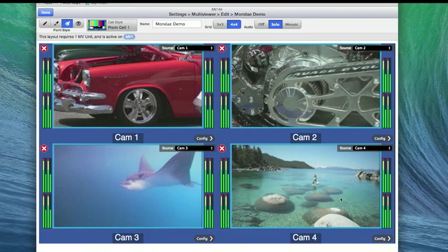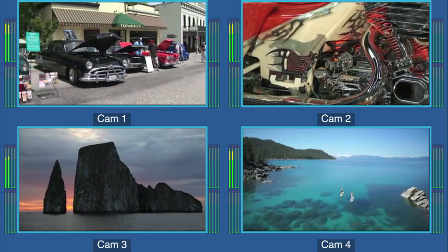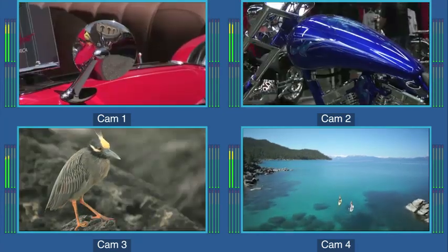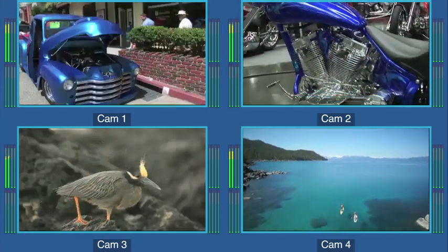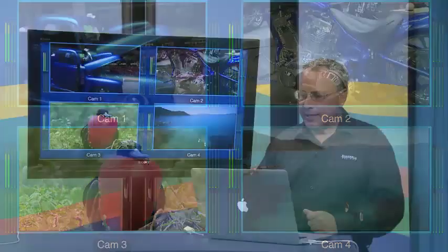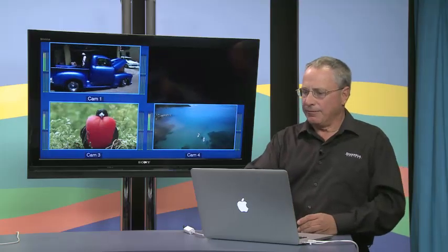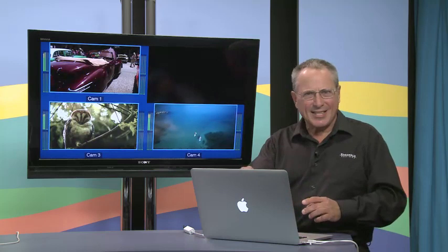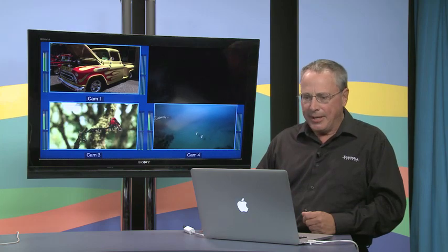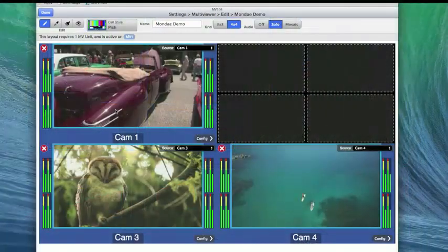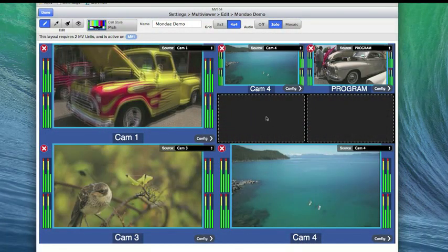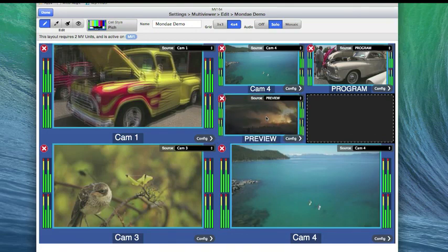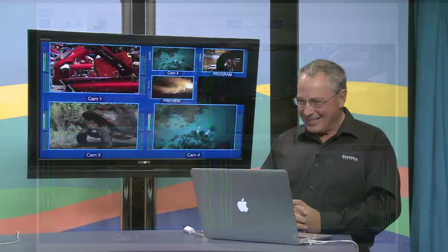Now, what happens then if we want to populate maybe smaller cells that way as well? Well, what we could do then is to say, I'm going to delete this upper right cell that's here, and I want to put 4 different little cells in here instead of having one large cell. So what I'll do is I'll select the cell style to be pitch. That's the one we just made a moment ago. And now you can see that I'm just populating each of these as we go along. Pretty slick, huh? Very easy to deal with.